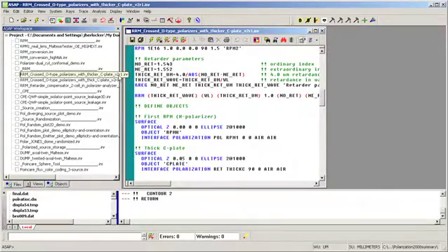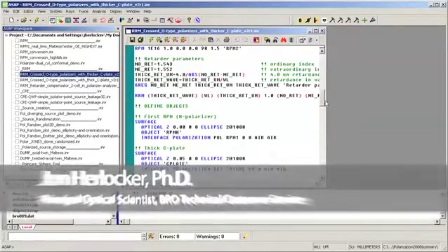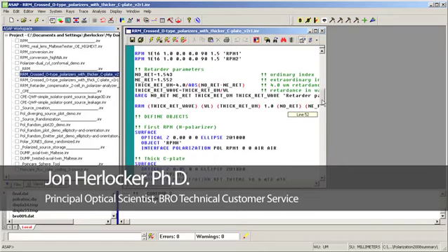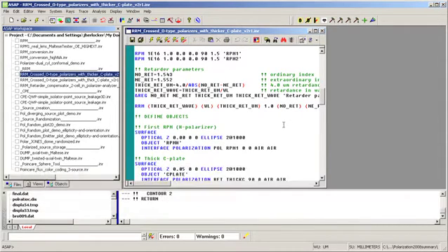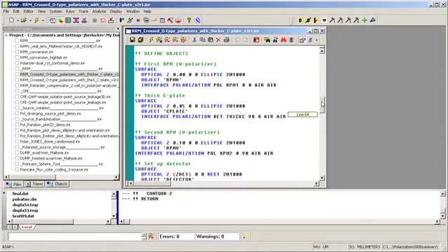The Realistic Retarder Model, added in ASAP 2008, is a complement to the Realistic Polarizer Model. It's a uniaxial crystal thin layer model. It's denoted by the command RRM to create it. It's applied to an interface using the interface polarization command. In this case, it's a retarder type.